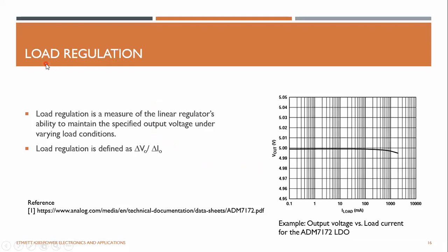The other characteristic is the load regulation. Load regulation, here you fix your supply voltage to any value and you change your load. So from no load current, very light load, to your maximum load current, you can change your load current and you can plot your output voltage.